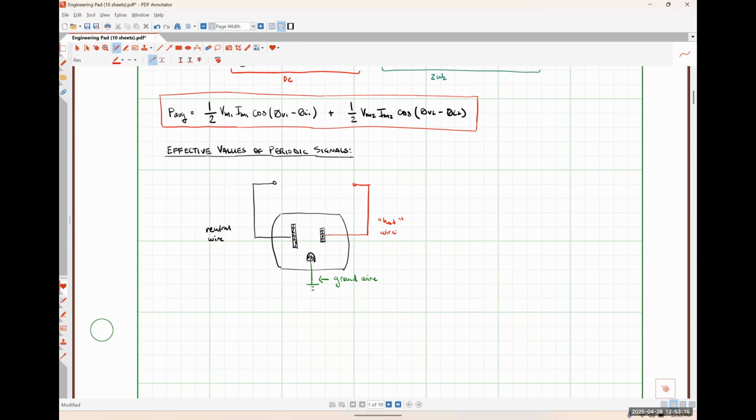This guy does not have a ground pin at all because it isn't needed for this particular piece of equipment. For other things that are going to handle significantly larger currents, they probably do have ground pins, and they also have different size blades on their plug to polarize things and connect it correctly.